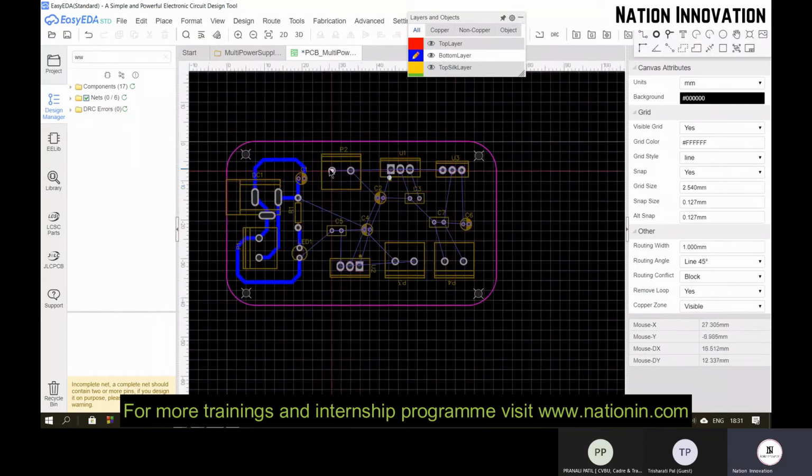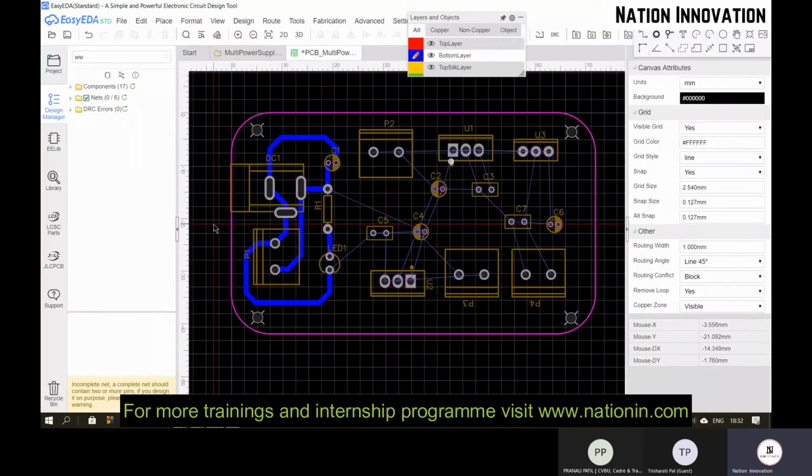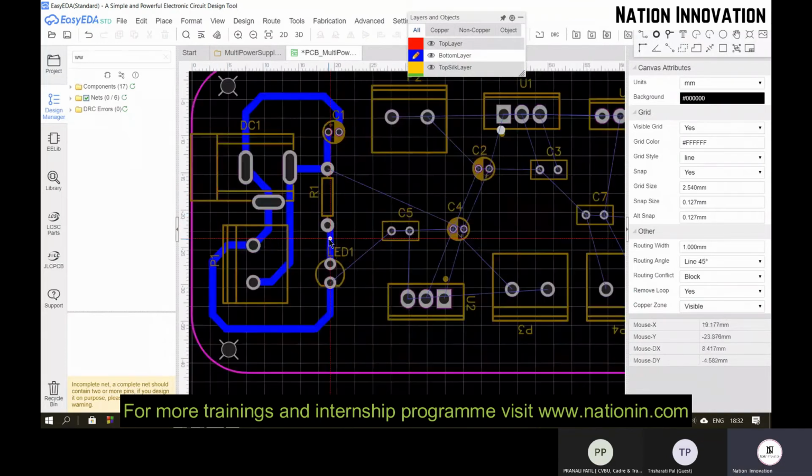If you want to reduce your width, you can reduce it now because all the DC power supply components are routed. But if you don't want to, you can go through with the 1 mm.